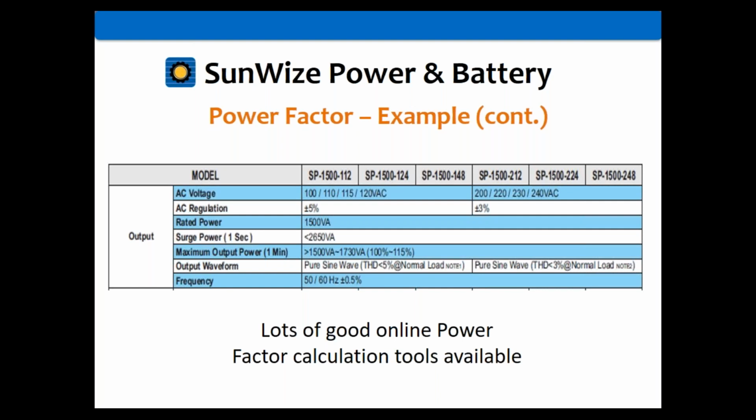So if you size your system based upon 12 watts, but you're really consuming 60 volt amps, that means your system is running inefficiently, and you may find your standalone power system failing because your load is inefficient. You don't realize it, but that inefficiency wasn't factored into your calculations, and all of a sudden you've got a load that is consuming 20, 30, 40, 50% more than it was designed for, and you're finding yourself shutting down in the wintertime. So something else to consider about this power factor. It's important to understand that.